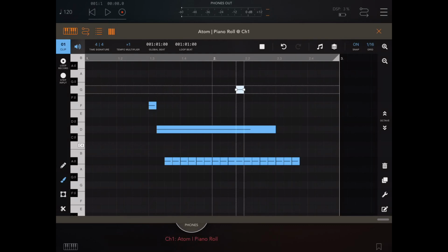Now, on top of this, it's worth noting with these tools that when you do select a note and drag it, there is an axis biasing. The axis biasing will work on your very first slight movement. So if your very first slight movement is in one particular axis, it will stick to that axis. Sounds a bit trickier than it actually is. Once you get used to it, it's a very powerful tool.